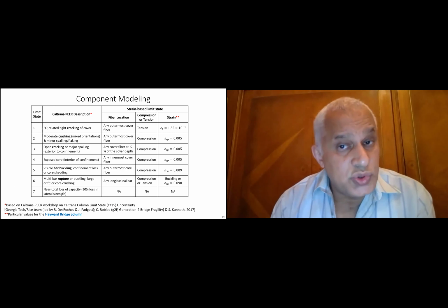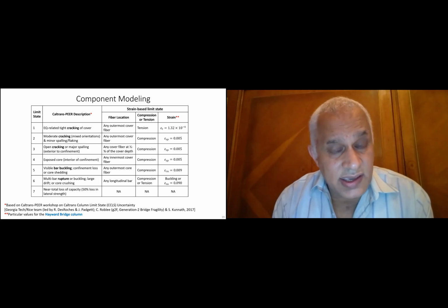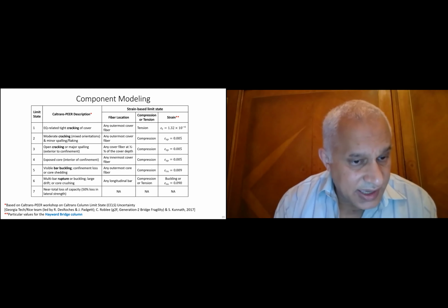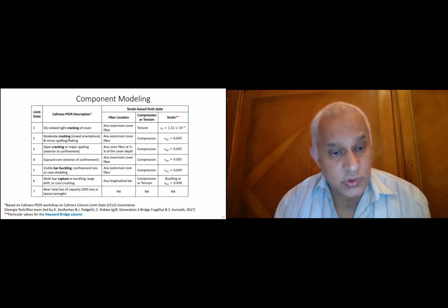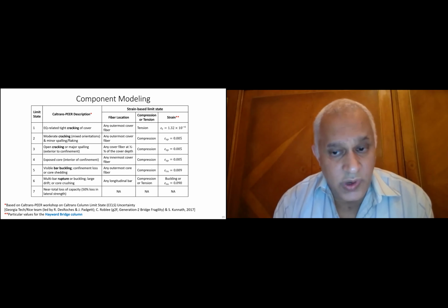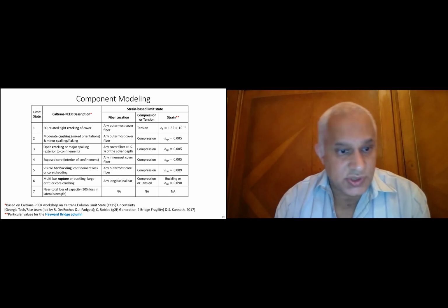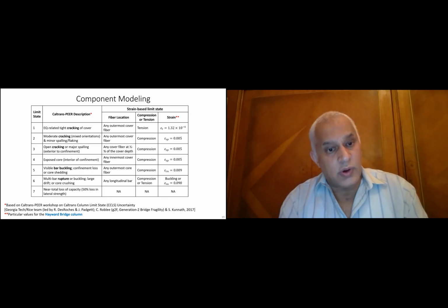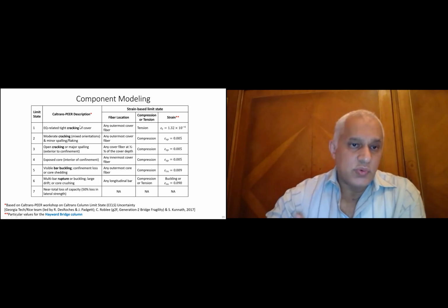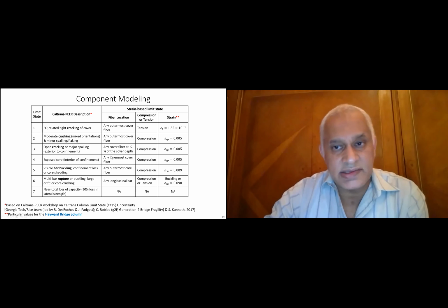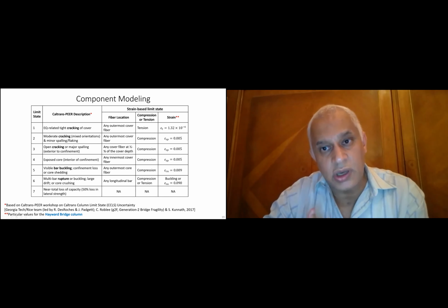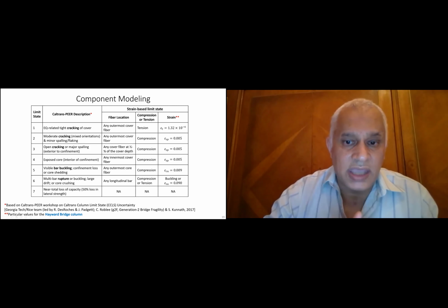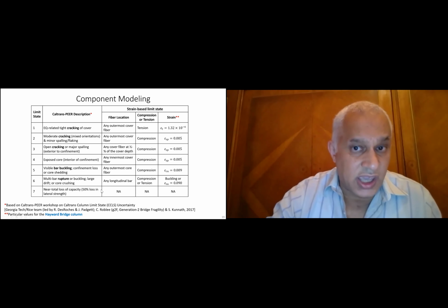We mainly use strain-based limit states based on the work that was done by Georgia Tech and the RISE team, and also Cliff Roblee in G2F. And this was presented through the work of Sashi Kunnath, who led a peer workshop. And we use the same 7 limit states. They have a good representation in terms of strain values, and we have specific values for the Hayward Bridge we are studying.